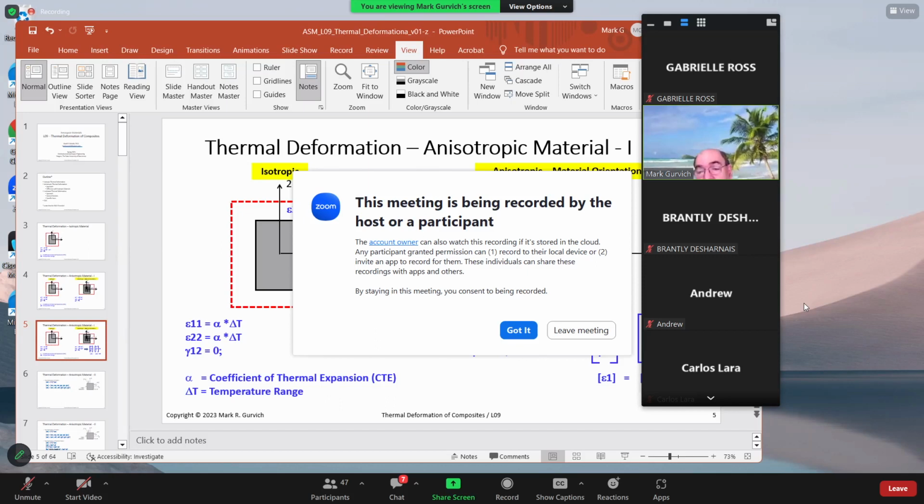And at the right, what we have is a matrix of thermal expansion coefficients for all directions. It again will be a one-dimensional matrix or vector consisting of alpha 1, alpha 2, and for gamma we just put 0 because something should be here. This one-dimensional matrix or vector should be multiplied by scalar delta T, as a range of temperature. So this matrix equation can be written as is shown at the bottom.